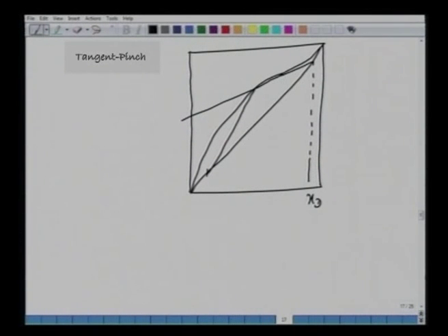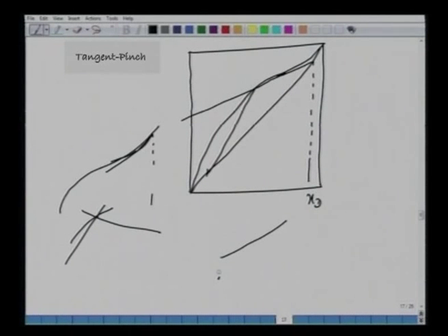All right. So in this case, similar to the absorption curve we had, one has to draw this pinch here, make a tangent wherever it makes a pinch with the operating curve. So if you have the slope like this and you are starting from here, then look for the tangent with this equilibrium curve. Unlike in the previous case, where we made an intersection of the two operating lines at the equilibrium curve, in this case one has to see where the operating line makes a tangent with this equilibrium curve. So that's the point where one should take this R minimum.